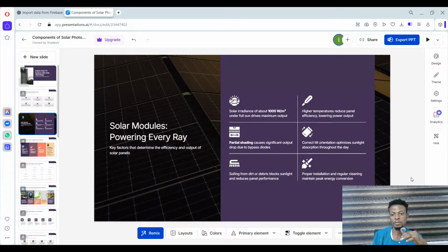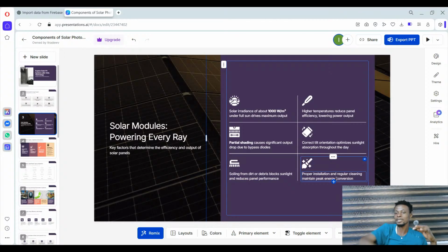Okay. So also, there's a way you have to properly place the panel so that it's directly facing the sun. That is the panel orientation. You don't just want to place it where maybe it's facing down while the sun is rising from it. No, you have to face it at an angle enough that the sun is blasting it directly. Right? This is to ensure that you get maximum efficiency from that panel.